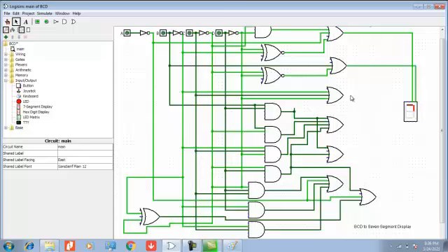And then for C, from here connect, come to the bottom. Leave one pin, then connect it to the next pin, because that pin is meant for your decimal point. We are going to display only a single digit, right?